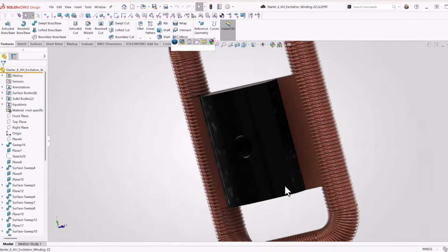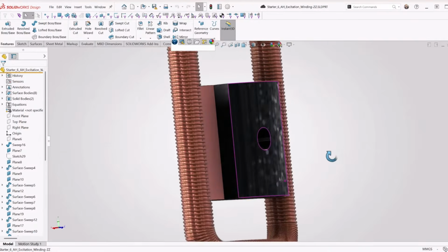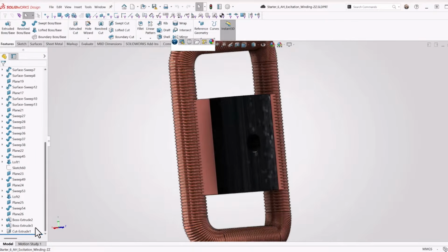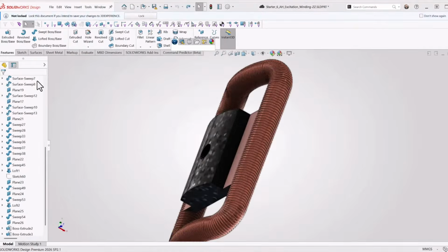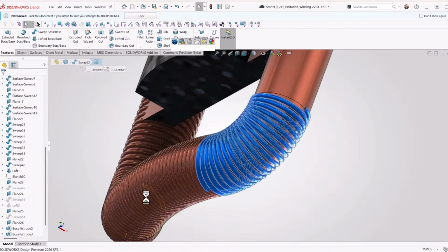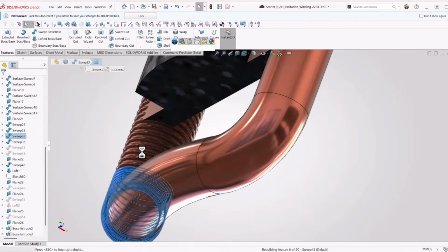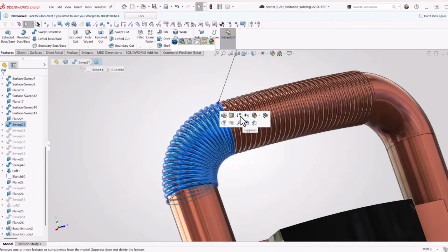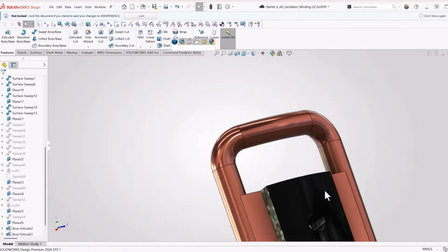Whenever you have a vendor component that you're pulling off McMaster-Carr, you want to see if you can suppress anything that's not necessary for the functionality. And then you also want to turn down the image quality. We were talking about that with graphics triangles, but inside of your system options on the document properties specifically, there is the image quality slider, and you want to make sure that's far off to the left. Don't have it anywhere near the red. It's not helping you at all.